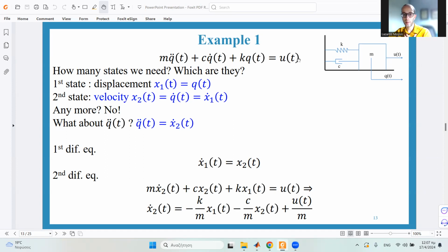This system is described by this second order differential equation. This differential equation includes Q dot and Q double dot. So we have displacement, the derivative of displacement, velocity, and the derivative of velocity, which is acceleration. Great. Now, in order to simulate this system in Matlab, I need to write two differential equations of first order describing this. This procedure is very, very easy. It's super classic in automatic controls and in what is called modern control theory.